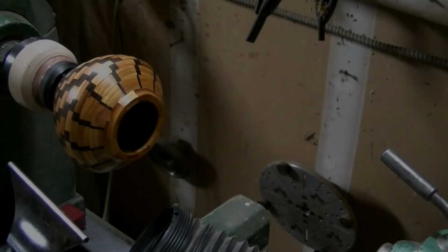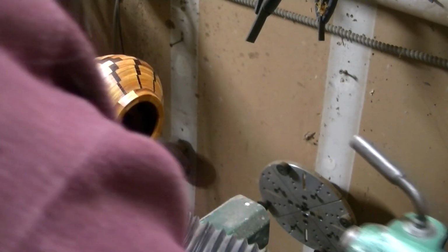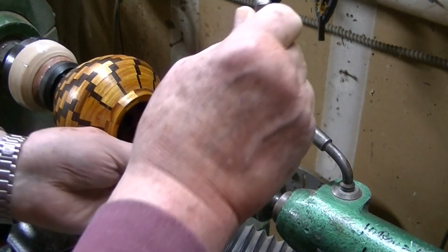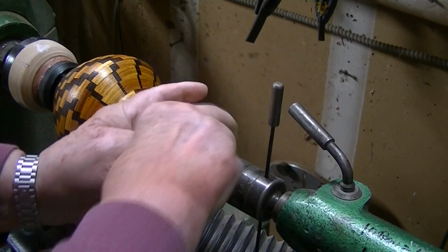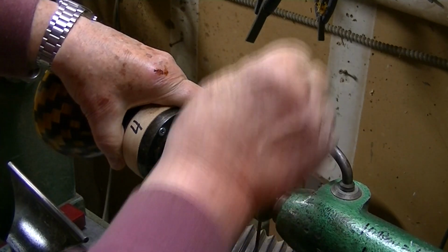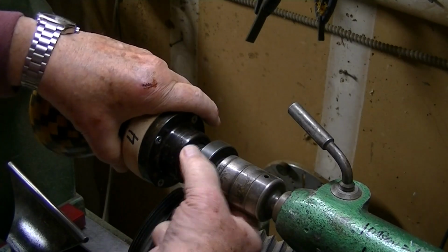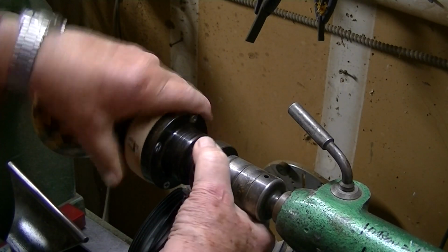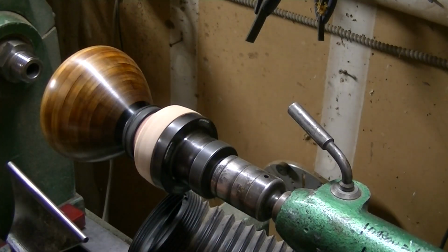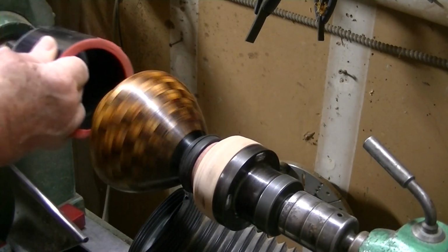And now the separation needs to occur. I need to take this project off of the glue block and free it. Here we're back to the live center system again. And I'm now going to move the vessel complete, faceplate and everything, onto the tailstock. This gives it perfect center and gives me some holding power. And once it's mounted, I'll be able to use it with my vacuum system, which then will push it into the vacuum chuck very well centered.